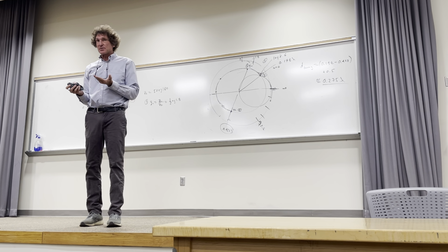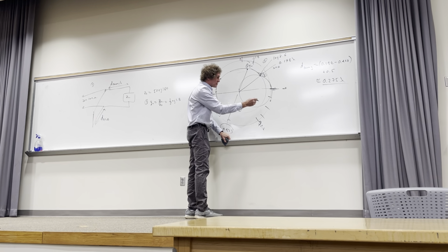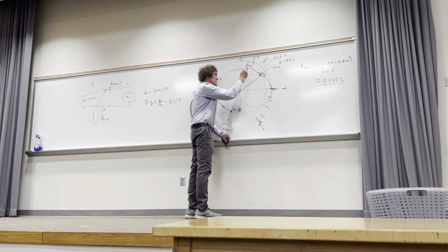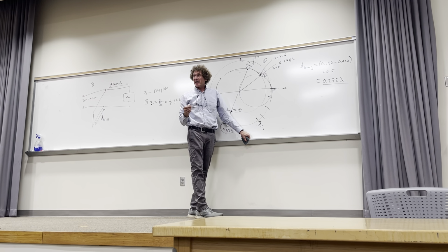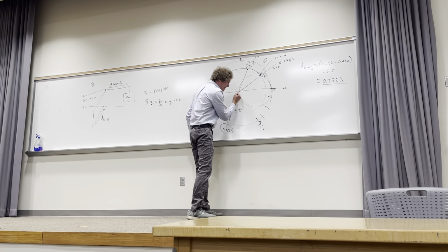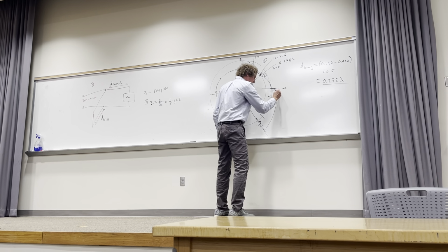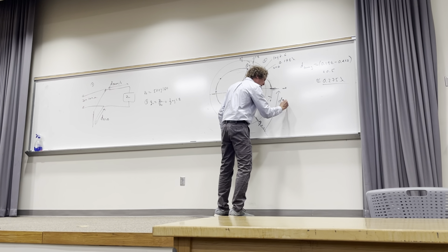Take a look in your Smith charts. Y'all see this? Here's the mistake that was made. A lot of people went to the point where they're on this trajectory and the 2.6 interacted, so they had something real minus J 2.6. That's not the correct point. It's just at the very outer rim, J 2.6. Y'all follow me? Then you shoot a line through here, and then this distance is the distance of the stub.